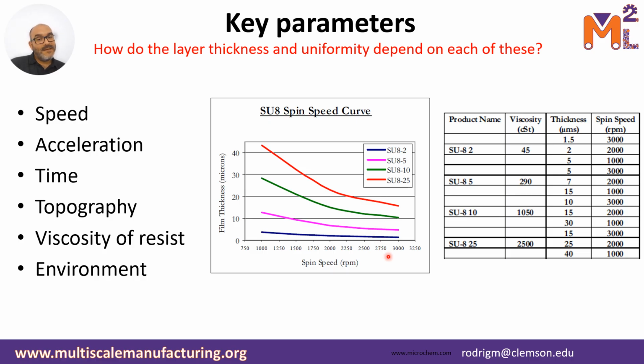You can imagine that one reason why spin coaters can start getting expensive is how accurate they are in terms of the spin speed, right? You could have a spin coater that tells you it has a target value plus or minus 500 RPMs. So for example, you tell the spin coater to do 2000 RPMs, it might get to 1500 or it might get to 2500.